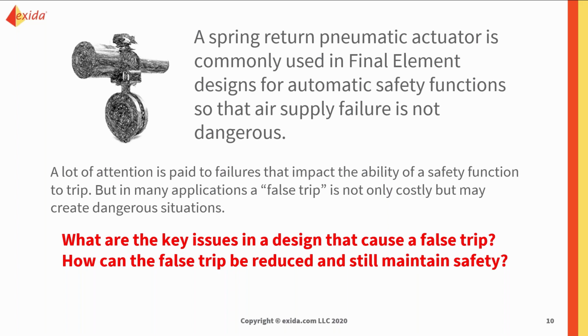And they're all going to include a spring return pneumatic actuator. Spring return actuators are commonly used in SIFs or the final element designs for your automatic safety functions, so that air supply failures are not dangerous. A lot of attention is paid to those dangerous failures that impact the ability of that safety function to perform if needed. If that dangerous condition occurs, you want your final elements to be able to shut down the process if necessary. So, as I said, most of the attention goes to those dangerous failures.